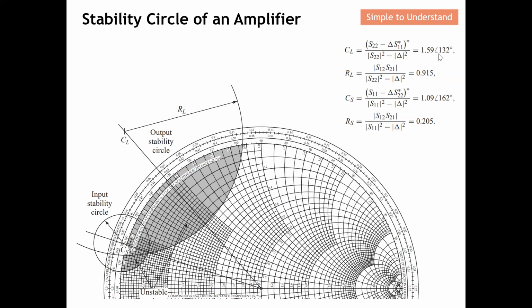What you're supposed to do is firstly look at the 132 degrees. If this is 132, and if you look at this number here, it's the angle from here to here. If you follow through this, you can see the angles here, 30, 40, 50, 60, 70, etc. You need to find 132, and you find this point, which is 130. So this point will actually be 132. What you need to do is cut from the point of origin, which is the point 1 of the Smith chart. You draw this line here. You draw this line first before you can actually determine all the parameters here.